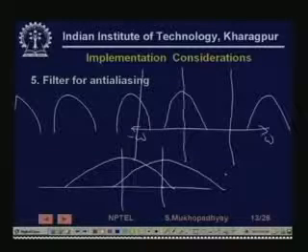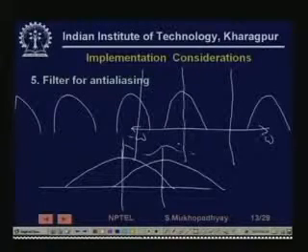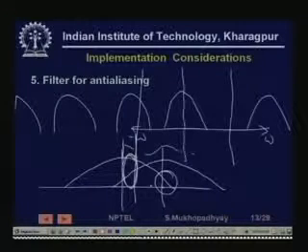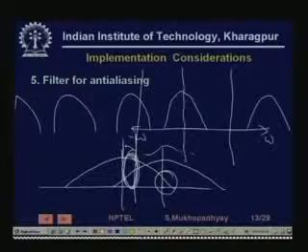So, what will happen is that effectively once these two lobes, if you take summation, then you are going to get a frequency spectrum of the digital signal that will look something like this. So, you see that, but this is a very important part of the signal. Generally for control, the low frequency part is very important. So, you see that the high frequency part of the signal, which was not so important for control, has got kind of folded back and it has come onto the low frequency part and is now affecting the low frequency part, which is important.